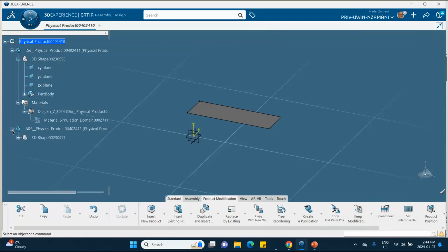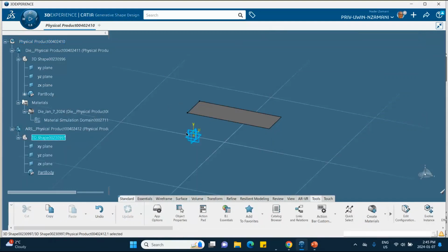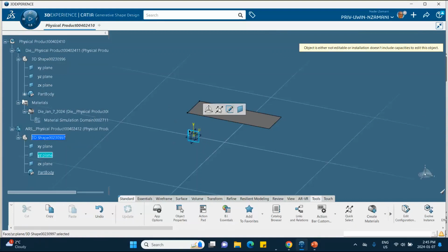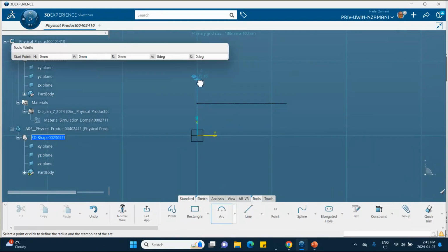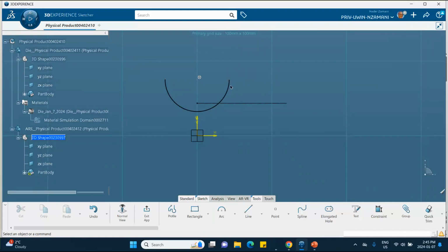and we make it. Double click on the shape on that vertical plane, on this same vertical plane. Yeah, on this one. I'm going to sketch half a circle. Notice that I did uncheck the snap to the grid point, so I'm going to have to fix this thing in a minute. So the radius of this thing is actually 20 millimeters. All right.